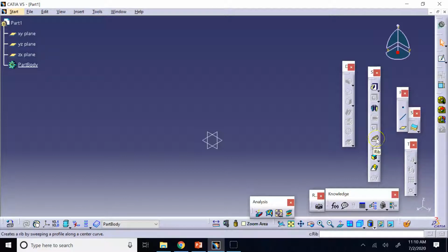And the guide sketch does not need to be a straight line. In Extrude, your sketch follows a line and creates a volume, right? Whether that line is perpendicular to the original plane or at angle, your guide profile is a simple line. Here, it can be way more complicated. It does not need to necessarily be a line.